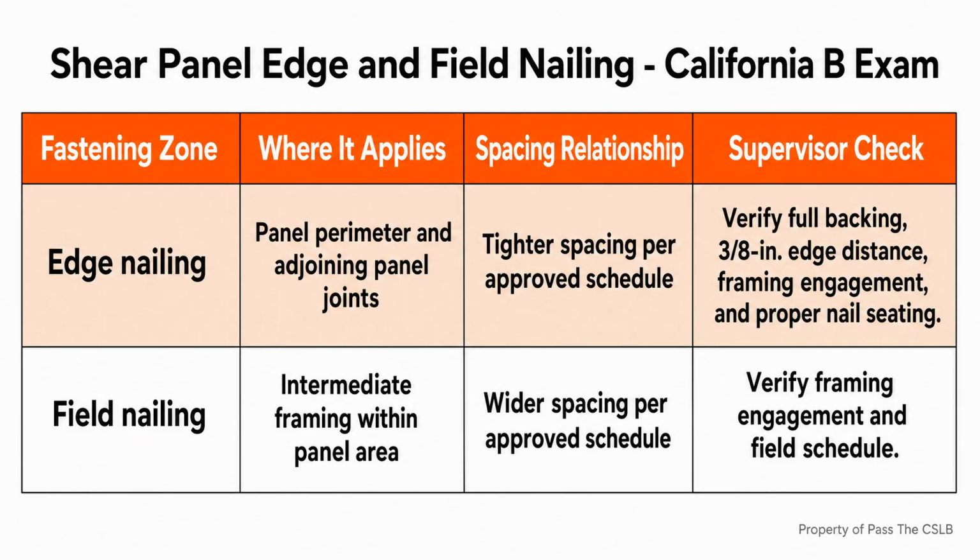The physical issue is straightforward. When a fastener is driven too close to the panel edge, there is less wood fiber between the nail and the open edge. Under racking force, that narrow strip can split or tear away. The nail may still be embedded in the framing, but the panel can lose its grip around the fastener. The connection then fails at the panel side.